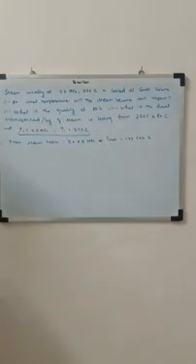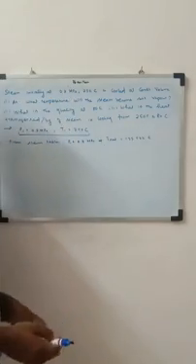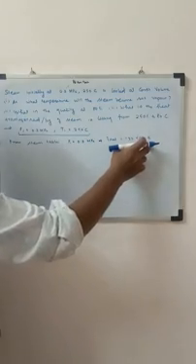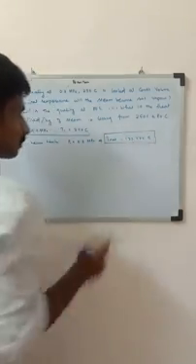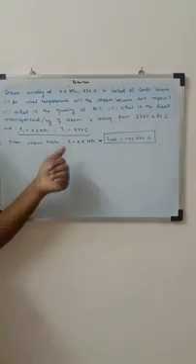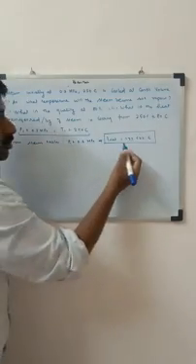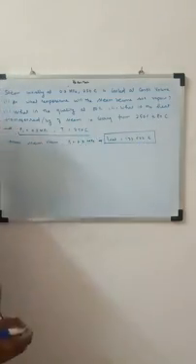That means when the pressure is kept at 0.3 megapascal, the steam will change its phase only when the temperature is 133. But our temperature is higher than this.